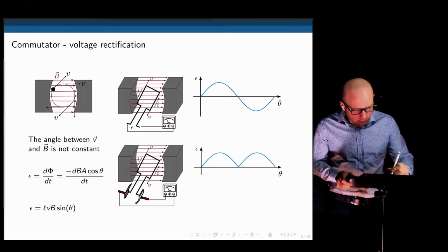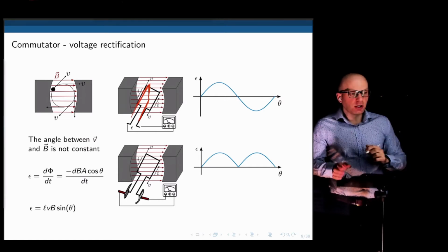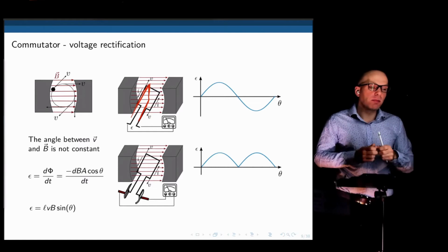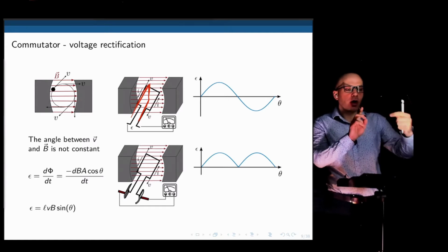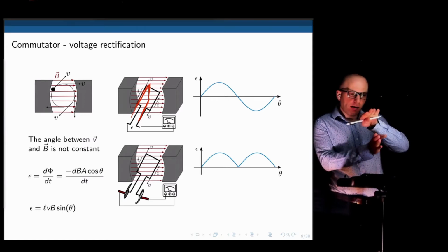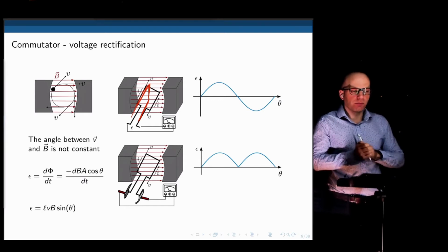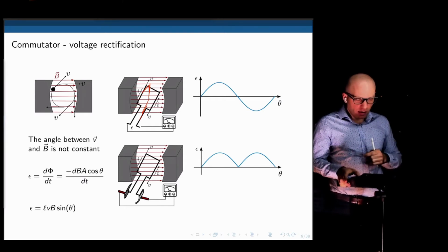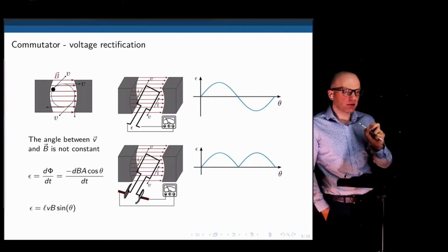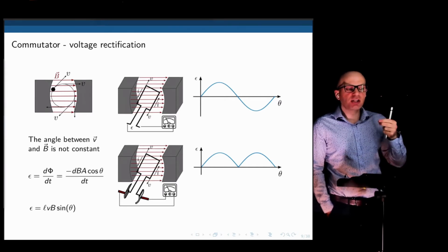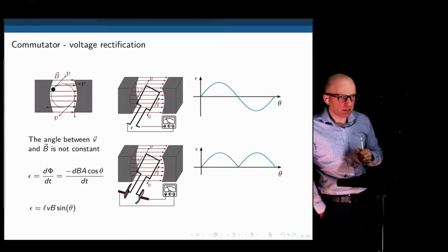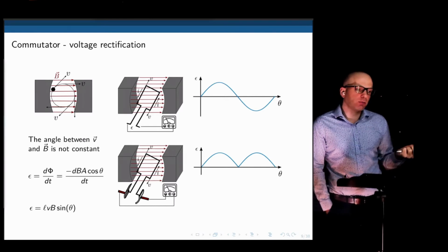Conversely, if we are now perpendicular or parallel to the magnetic flux in a configuration like this, then at that specific instant in time, we are moving along the lines, even though it's a rotation. At that point, the top wire and the bottom wire are moving parallel to the lines of the magnetic flux, which means that the generated EMF is 0 at that instant. They don't see any change in magnetic flux at that specific instant in time. This means that the cross product will be 0.